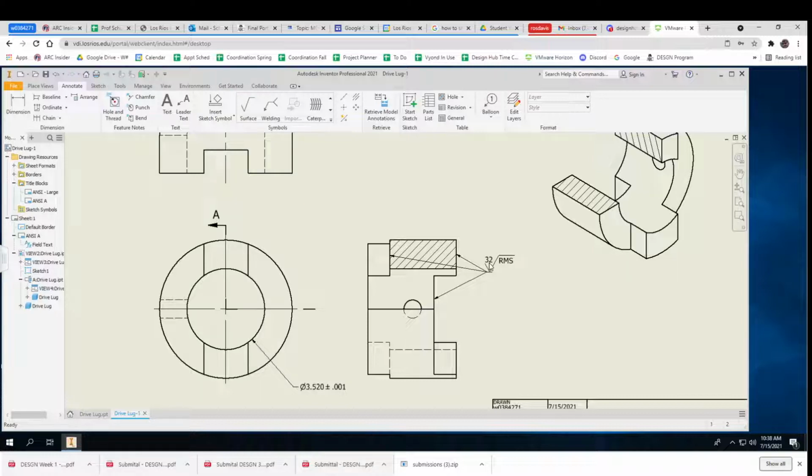That's a very, very good milled surface or a very, very good lathe surface. 125 is like you're just running it over to get a dimension. A 250 would be a roughing cut. And root mean square is a mathematical model they use when they're doing laser type inspections.